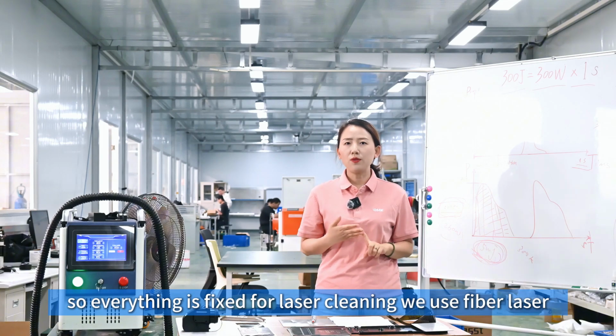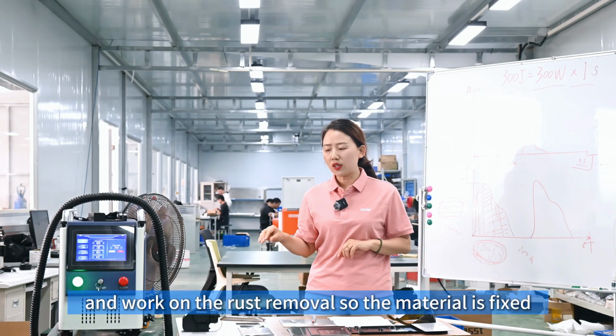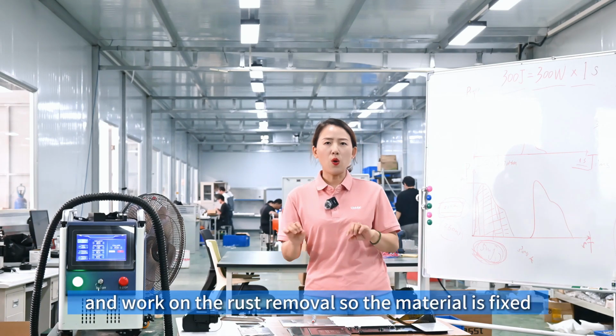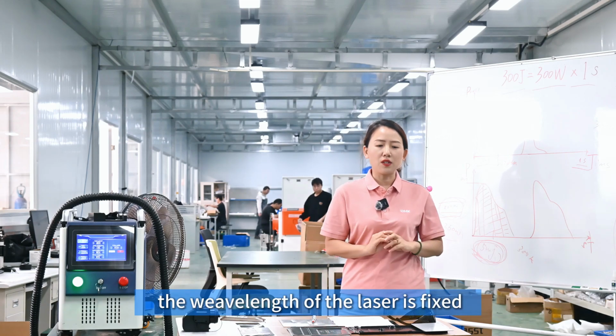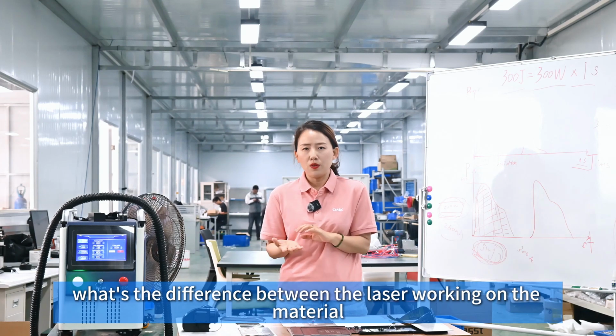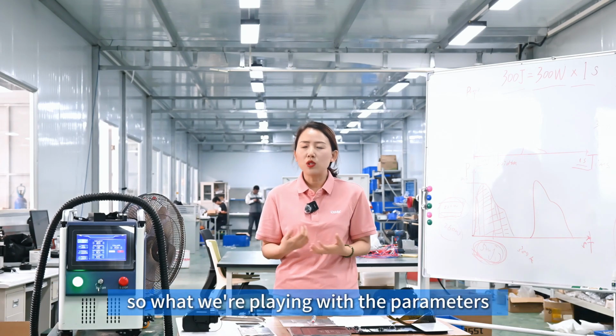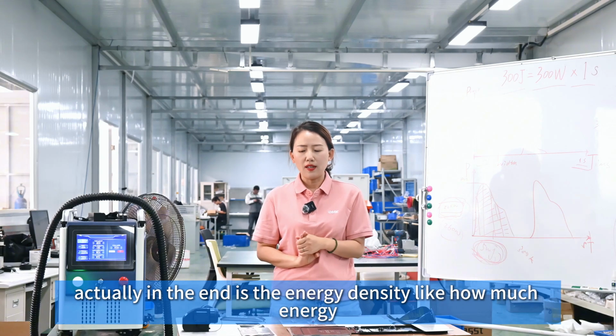We use fiber laser, which is 1070 nanometer wavelength, and work on rust removal. So the material is fixed. The wavelength of the laser is fixed. So what's the difference between the laser working on the material? What we're playing with in the parameters, in the end, is the energy density.